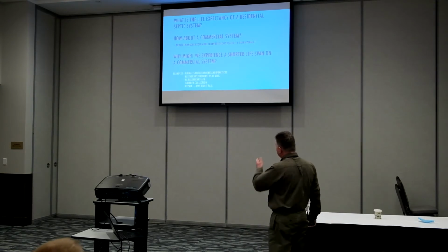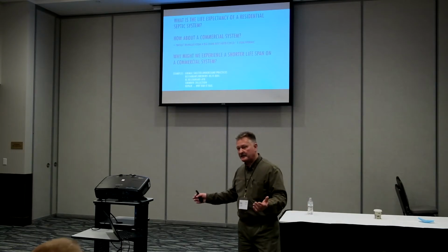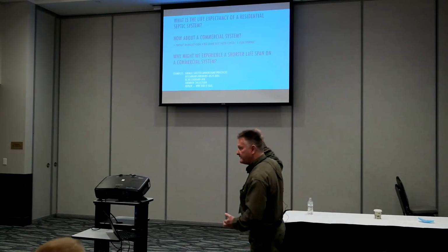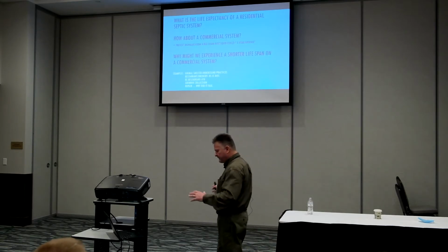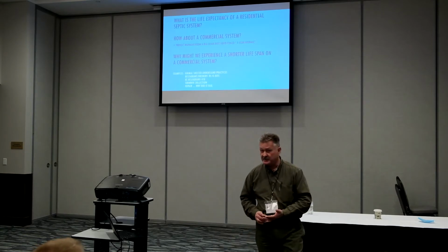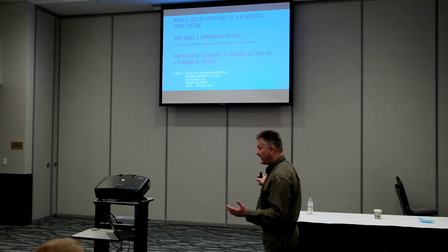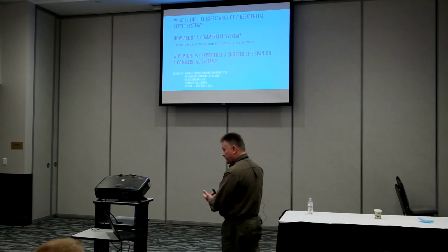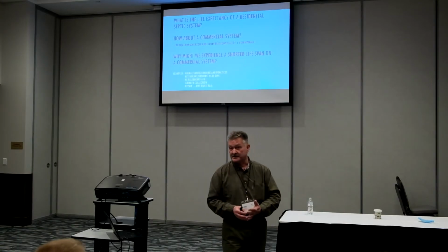So, for example, we need to understand the practices within the particular facility. I was involved in an animal shelter. They're designed by square footage, number of bathrooms, and so forth. But in the design, they really need to pay attention to what is the operation inside that dwelling. In this particular case, they failed to recognize that there's 2 commercial washing machines going 12 hours a day.